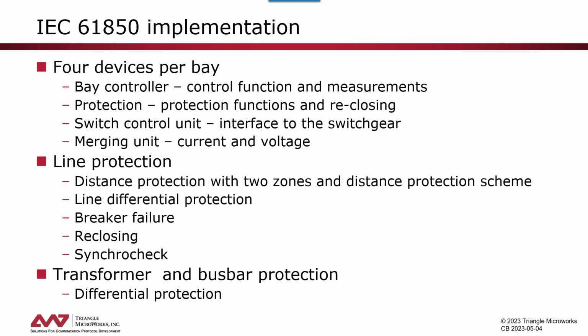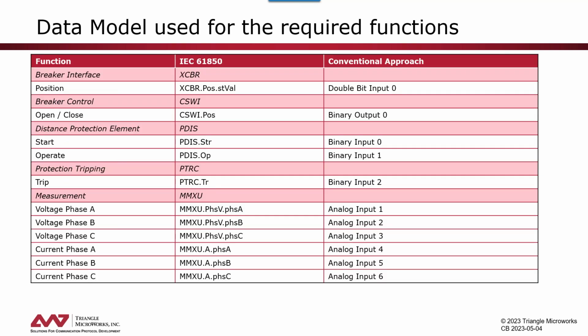As a little reminder on the IEC 61850 data model that we discussed last time, that's an extract of the data model that we use for our application. So here we see the 61850 model for some of the different functions and signals. Here we would see how this would look when we would model it in DNP, the different kind of data that we would have as DNP points.